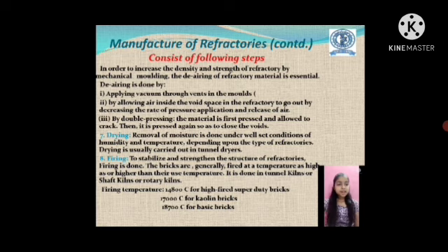To stabilize and strengthen the structure of refractories, firing is done. The bricks are generally fired at a temperature as high as or higher than their use temperature. It is done in tunnel kilns, shaft kilns, or rotary kilns.